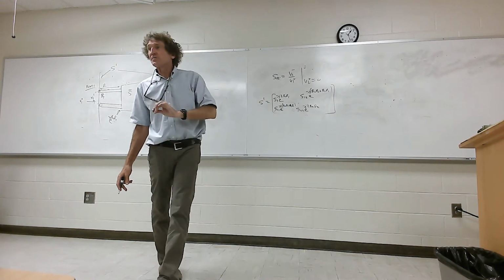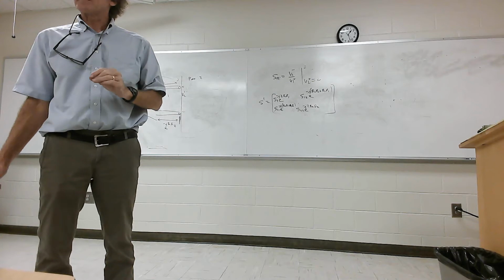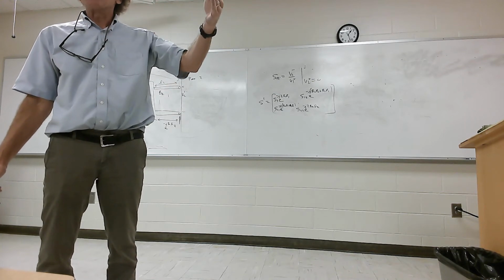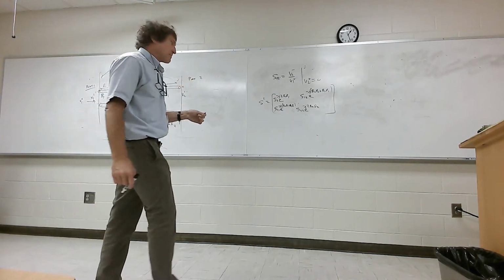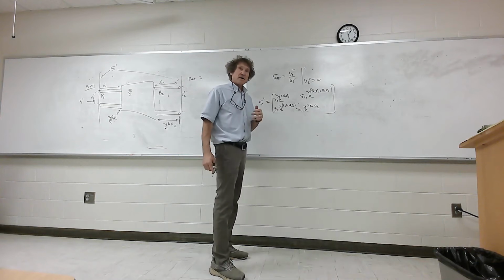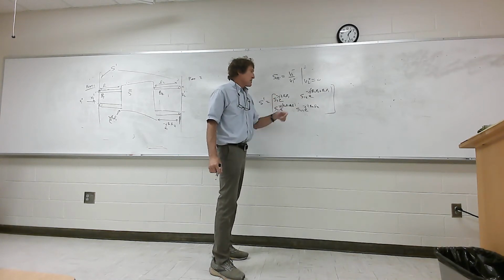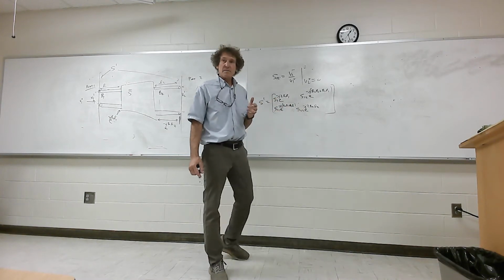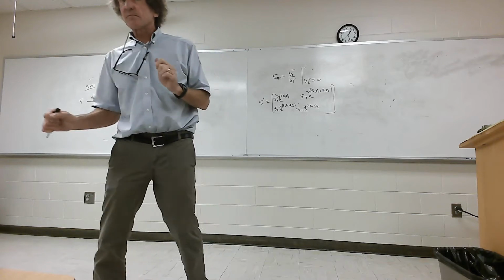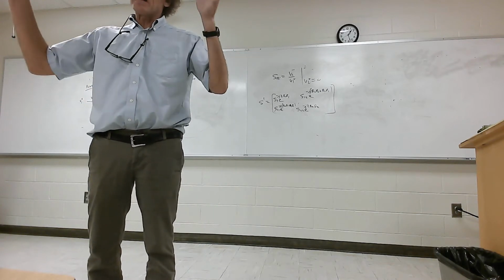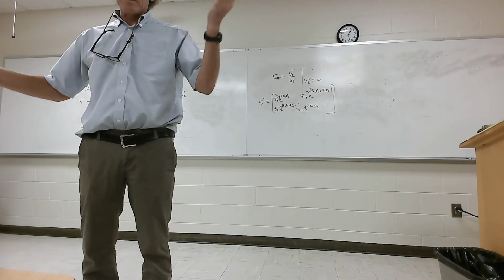Beta is a function of frequency. So one thing you have to understand is, as you raster the frequency, you have to change the value of beta every time, because beta is 2 pi over lambda, and lambda will change versus frequency. And the same here, but you can extract these values very quickly. In most modern programs, once you give it the lead length and stuff like this, they can just pop out the actual S parameters without any problem. I mean, the modern equipment.